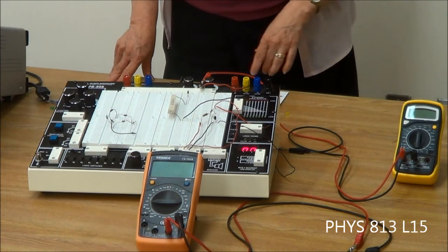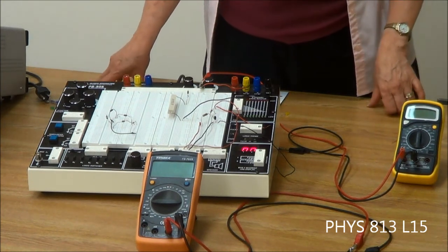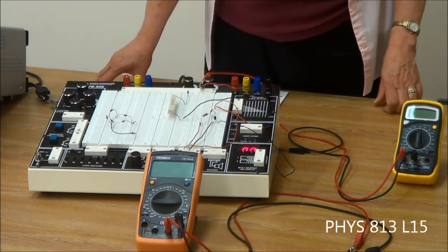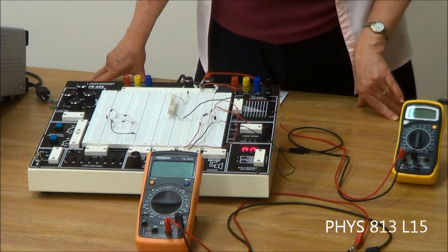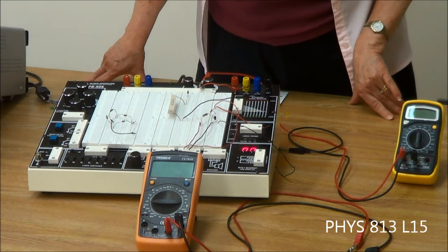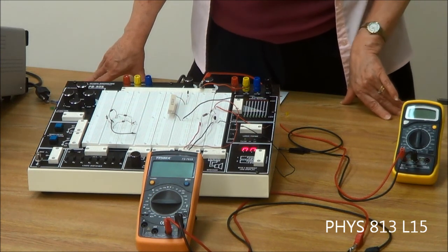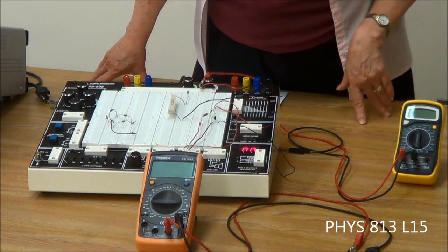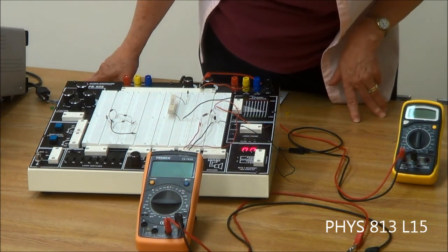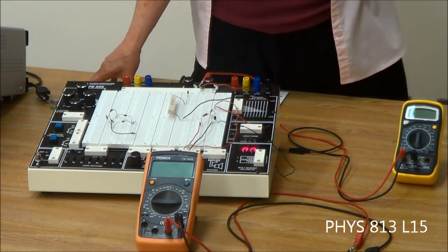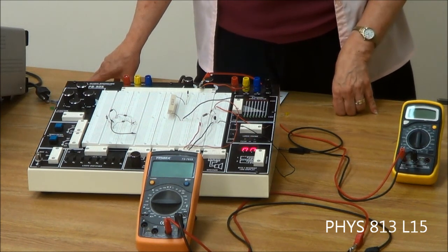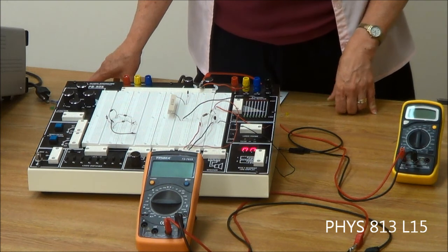Now on page 128 under notes, there's a couple of things about this. In some of these you are going to have close to 200 milliamps or possibly a little bit more. And I know from experience that when it gets close to 200 milliamps, it can burn out the fuse in the meter, and you really don't want to do that.